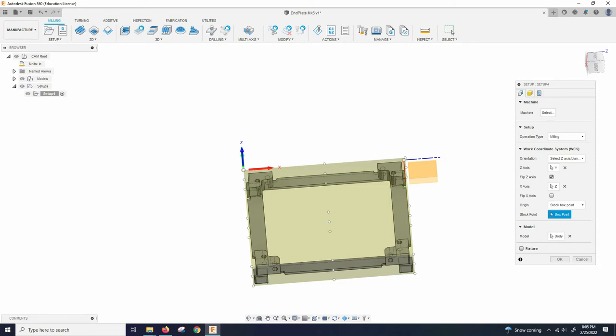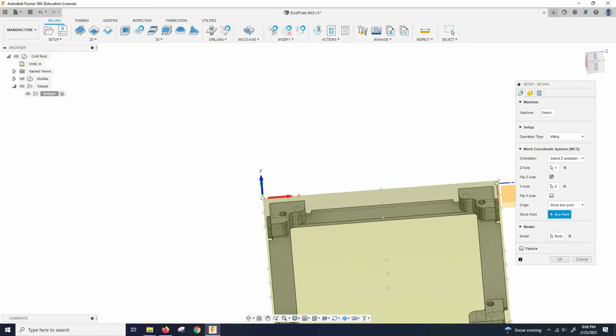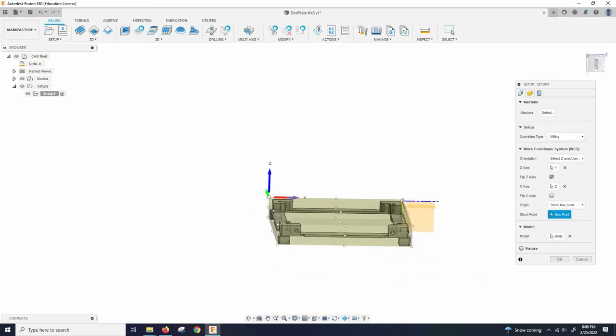There's also a fixture plate bolted down to the plates we have here, and on that fixture plate has a magnetic stop that you can use. So if you're going to make 4 or 5 of these in a row, you can just line it up to these two surfaces basically, and you don't have to re-edge find between each part. You can just slap them in and you're good to go. And then your Z should be on top, especially for this first half, because it's easier.